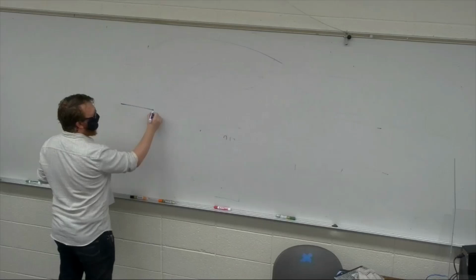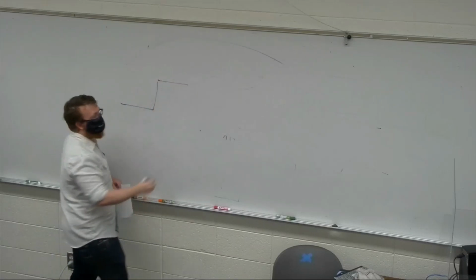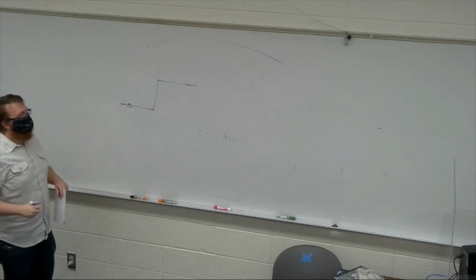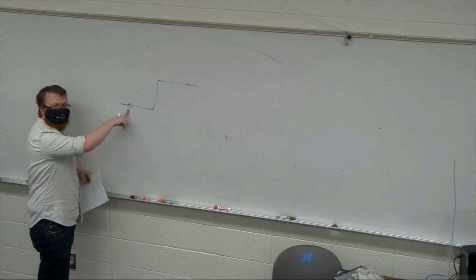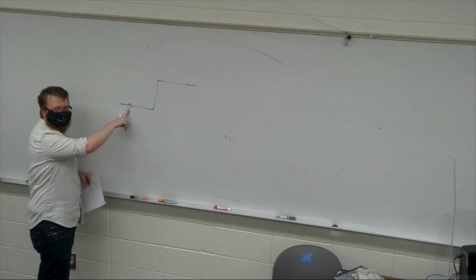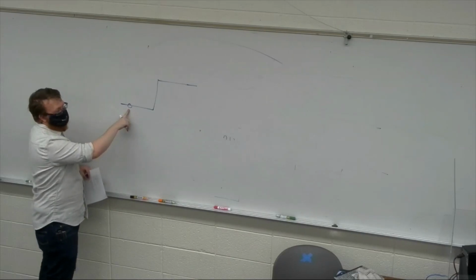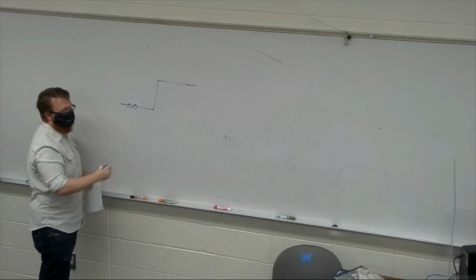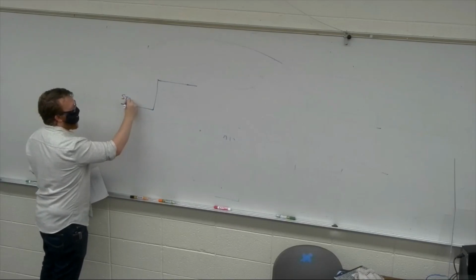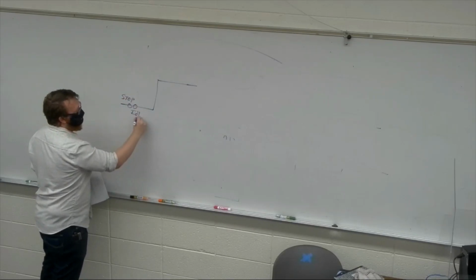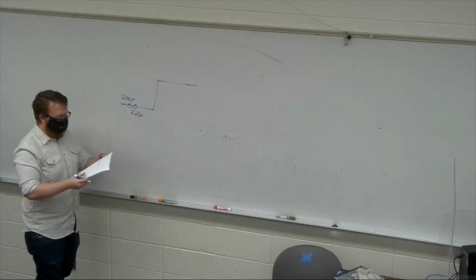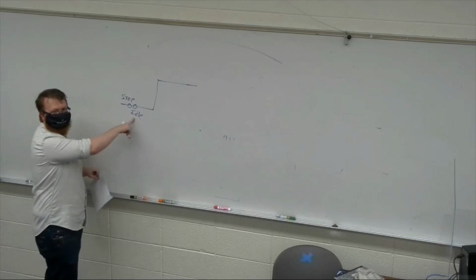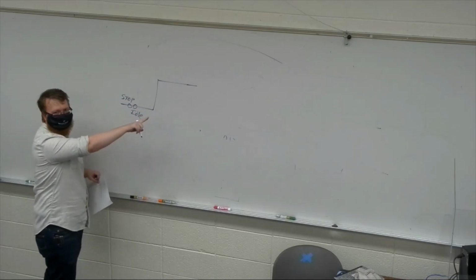The last bit is 0. Stop bit is 1, right? So you stop here, and at this point it enters stop bit. One 100 megahertz clock cycle later, it enters idle, because there's no countdown in my stop bit. So basically it instantly enters idle compared to the slow baud rate.